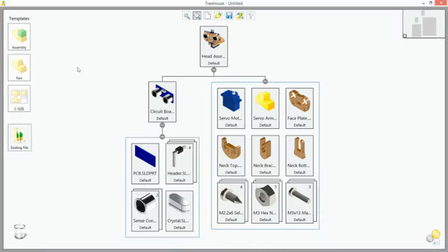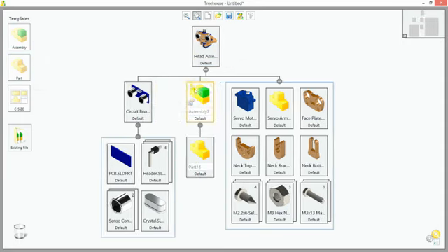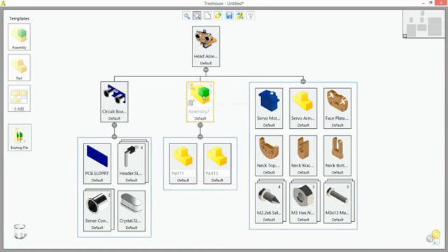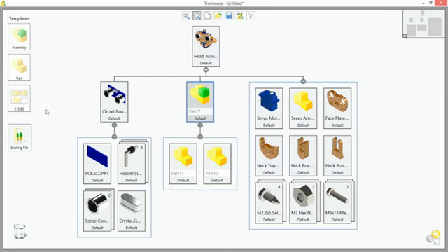Solidworks Treehouse is a new standalone application for building new and managing existing assembly structures using an intuitive graphical interface. By simply dragging and dropping parts and assemblies onto each other, you can build up your assembly structure in seconds. Each part or subassembly can then be edited to include custom properties, configurations, and quantities. Drawings can also be added to both parts and assemblies. When complete, the entire structure can then be exported into a full Solidworks file structure.